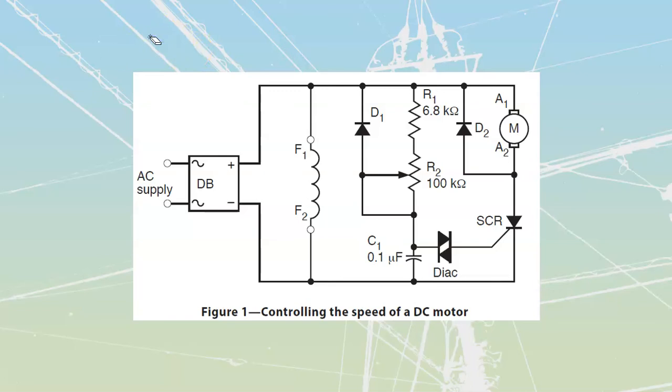Okay, let's take a look at this one though over here. This one, what we are going to be controlling is a motor part over here called the armature. Since we're controlling the armature, therefore we must be looking at controlling this thing between 0 all the way up to its rated speed. We've got another motor component inside of here, which is this F1 and F2. F1 and F2 is just going to be the shunt field.